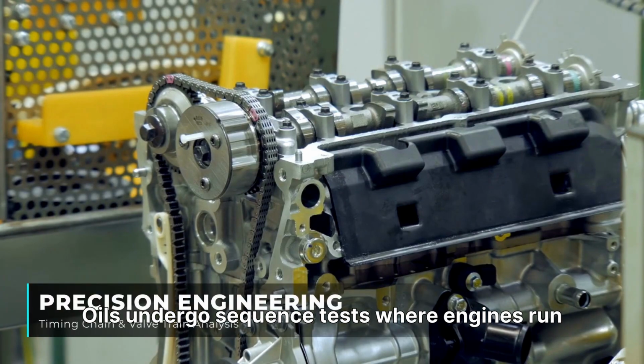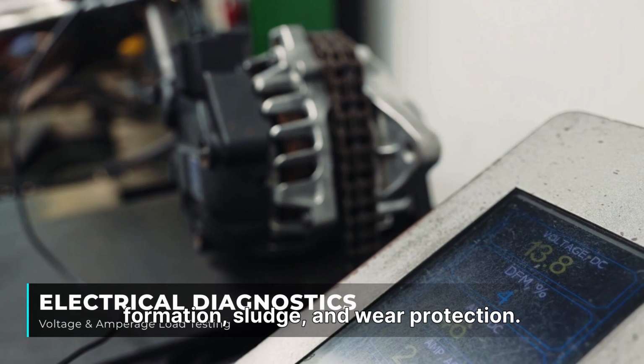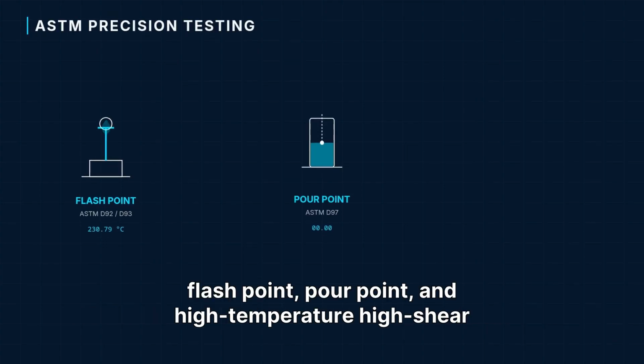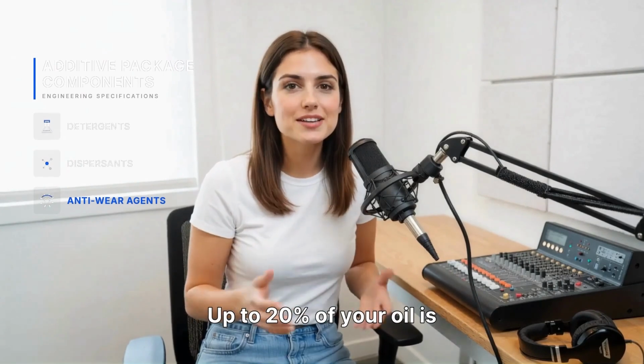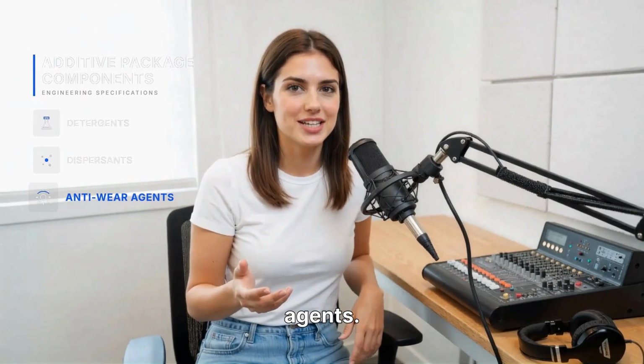Oils undergo sequence tests where engines run for hundreds of hours to measure deposit formation, sludge, and wear protection. ASTM standards define precisely how to measure flash point, pour point, and high temperature, high shear viscosity. But base oil is only part of the story. Up to 20% of your oil is an additive package: detergents, dispersants, and anti-wear agents.